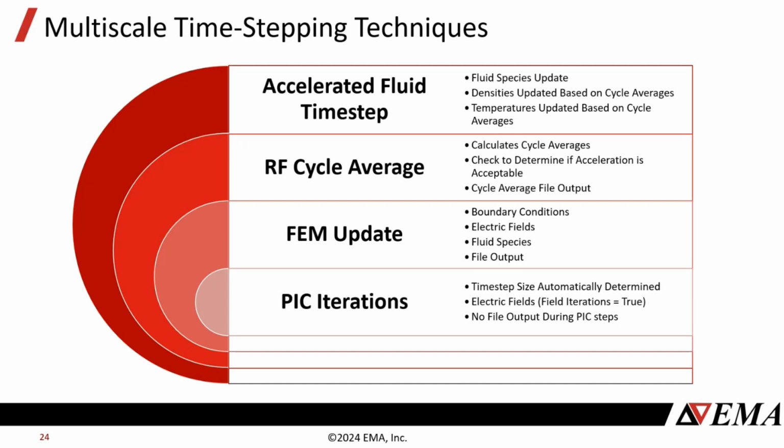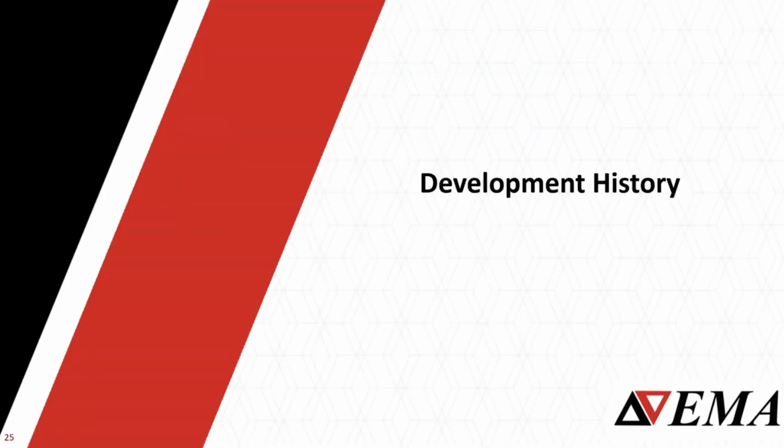And then we can accelerate even further through, let's say, a macro scale time step to be able to understand how the fluid flows through the system and how deposition happens on a much longer time scale based on some extrapolation that we can do at each RF cycle steady state that we get in the system. So a lot of this is automatic in the solver. The information that you set in the user interface is the size of the RF cycle and the acceleration time step that you want to take. But the PIC will iterate to be able to reach its steady state and run these simulations efficiently.